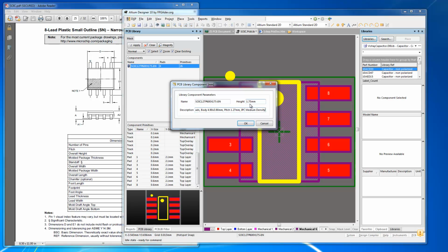There is also a height over here. It's a default height. It's actually kind of legacy from the old 3D. But it's information that it can use in the event you do not provide a 3D model for this. Altium can use this. It's better to use the model, especially if you have situations where it's an unusual shape, because Altium can do a better job of calculating and showing those clearances, or if there's something that's going to abut against each other. But this is a bit legacy, but it can use it as a part of its design rule set.